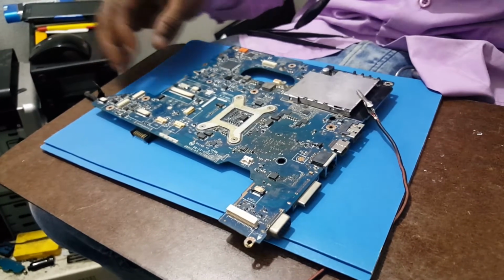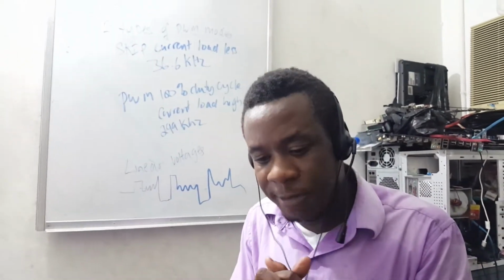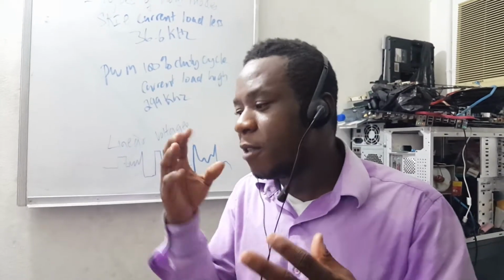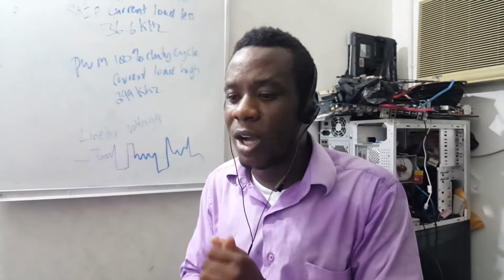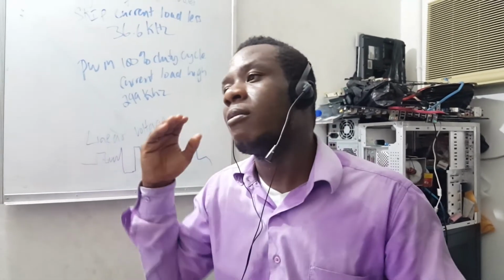In the next class, we're going to do the working conditions of the I/O controller, how it communicates with the BIOS, and how to use the oscilloscope to measure the BIOS pins to ensure that the I/O controller is correctly reading the BIOS, right? And the adapter present signal, the supply, reset, and clock. Then we're going to go to the trigger. We're going to learn how to understand the resume well reset, or RSM reset signal, which goes to the PCH to start the first reset signal on the board. RSM reset is the first reset signal generated right after the trigger. That is what we're going to do in the next couple of classes.